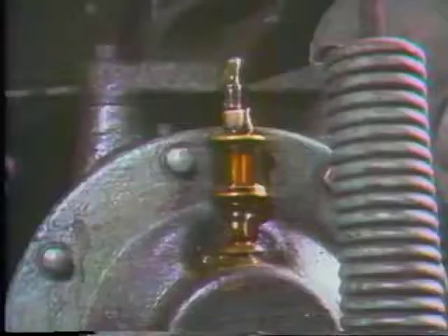Oil filters and coolers are often used in a forced lubrication system. Filters keep the oil clean by using a filtering medium, such as bags or screens. Coolers remove heat that the oil picks up from the bearings. So, a forced lubrication system actually accomplishes three things. It lubricates the bearings, it keeps the oil clean, and it keeps it cool. There's usually a sight glass on the oil reservoir. If the oil level gets too low, oil has to be added.